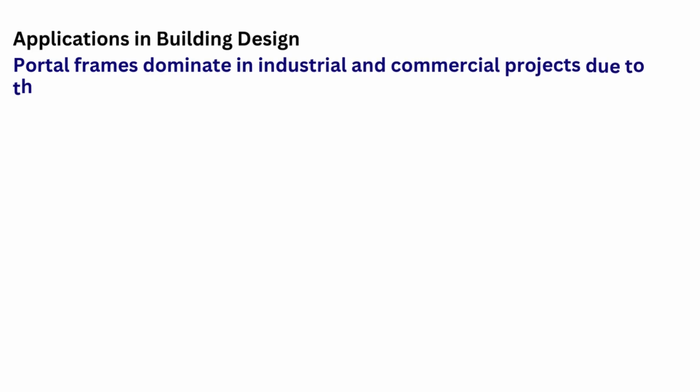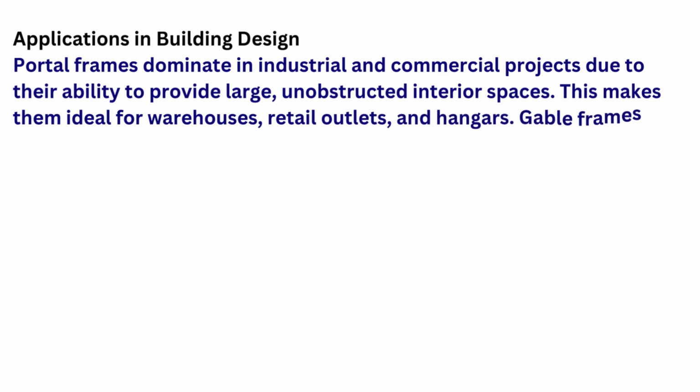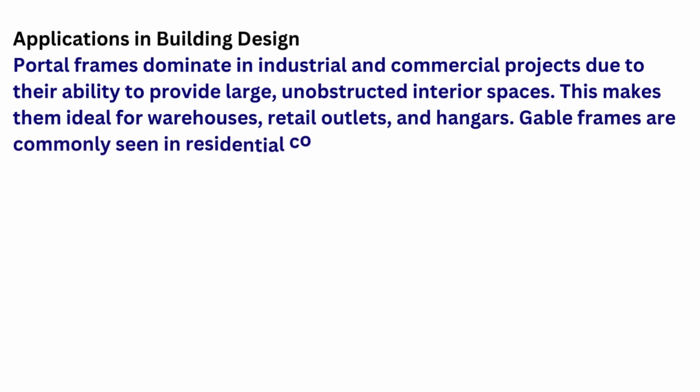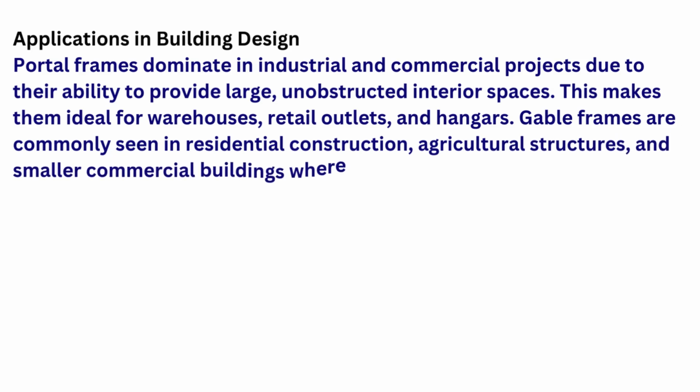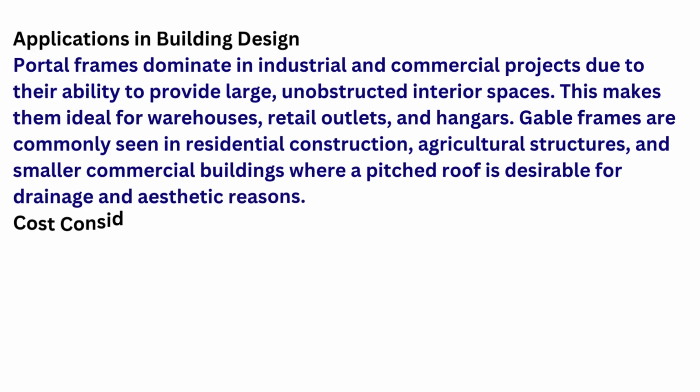Applications in building design. Portal frames dominate in industrial and commercial projects due to their ability to provide large, unobstructed interior spaces. This makes them ideal for warehouses, retail outlets, and hangars. Gable frames are commonly seen in residential construction, agricultural structures, and smaller commercial buildings where a pitched roof is desirable for drainage and aesthetic reasons.